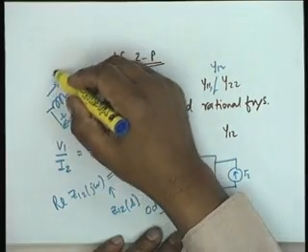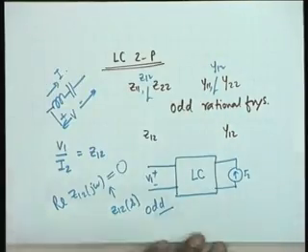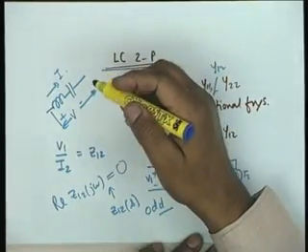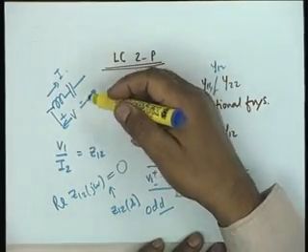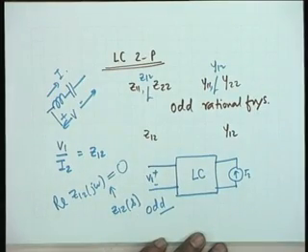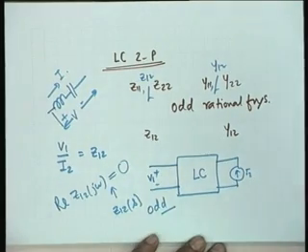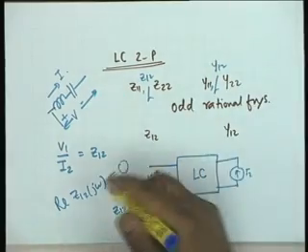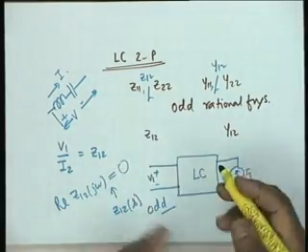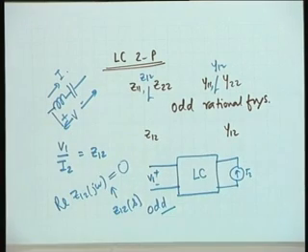Then the impedance is 0, which means that the ratio of voltage to current is either 0 or infinity. In other words, at that point it has a pole. We are not talking of a pole or a 0. We are talking in general. If the function has a pole, all LC parameters have to have poles on the j omega axis only.